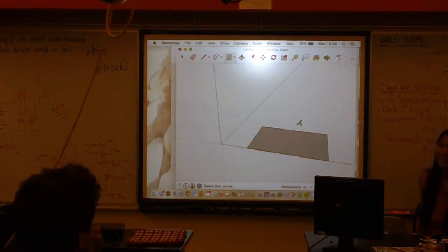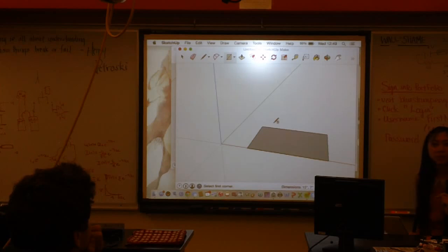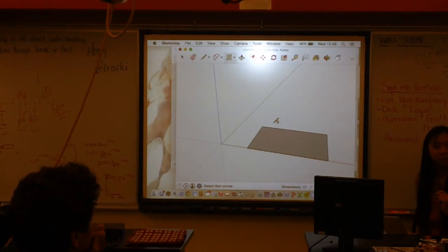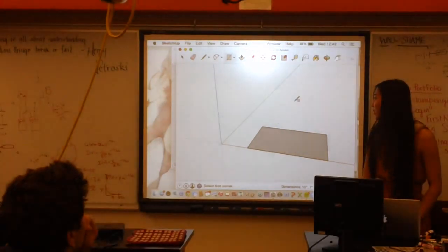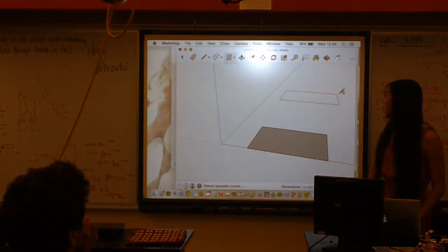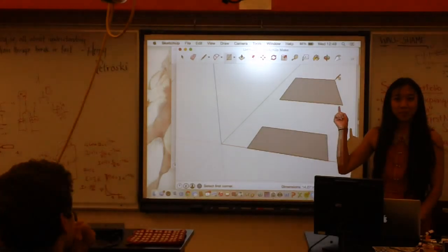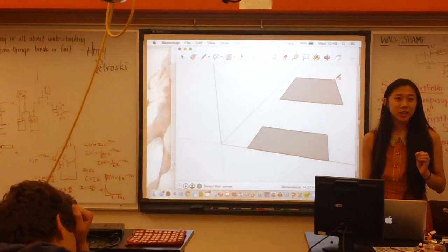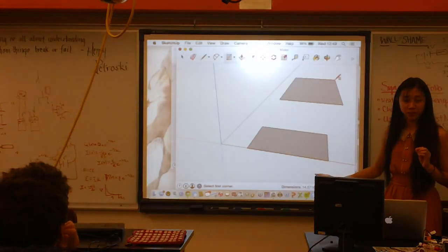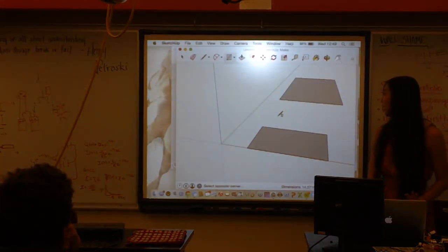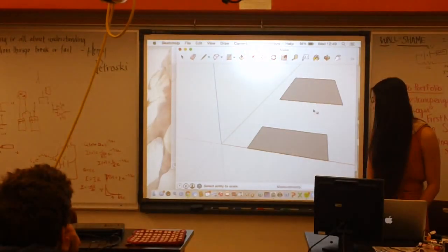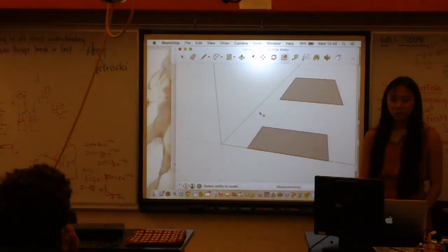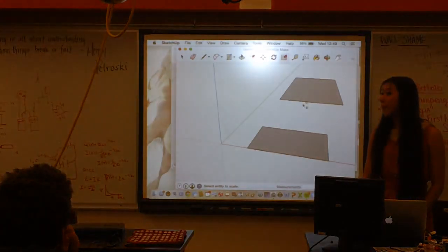On the PC, however, it doesn't let you just draw the rectangle and then edit it. Actually, Maya and I just discovered this today. And so what you want to do is you have to draw it, and then before you click it to make the rectangle actually there, you have to type in the dimensions. So as you can see, when I draw a rectangle, I can click a point and then click another point, and that's where it ends. If you're on a PC and you're editing the text inside the dimensions field, you need to click a point, and then as you're dragging, at this point, I haven't clicked yet, you need to enter the new dimensions. You don't do that on Mac, so that's why it didn't work this time. It works on the Mac.